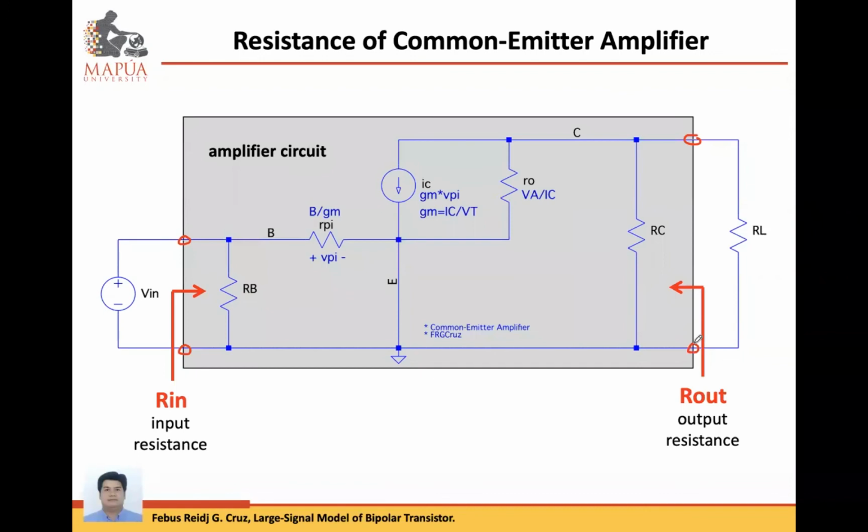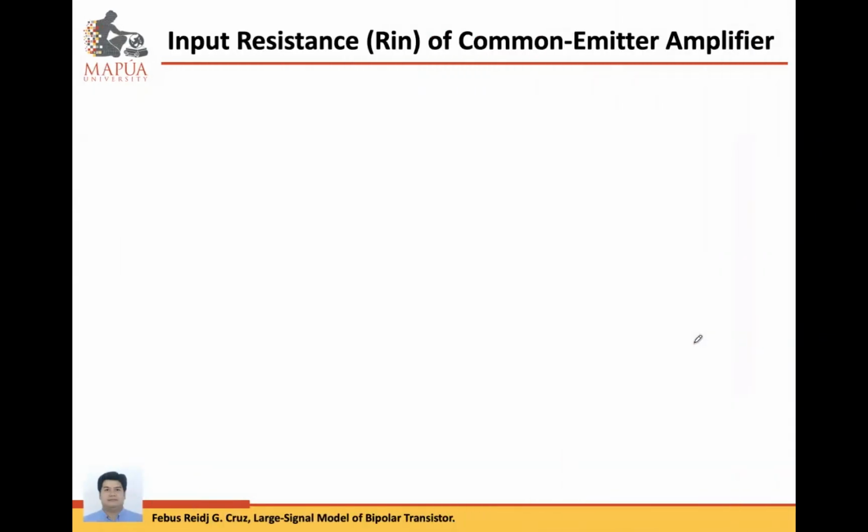Okay? So, ganyan yan. But, when you do the measurements, ito yung reminder. For the input resistance, so this is the amplifier circuit. If we want to determine the input resistance, we are going to remove the AC input voltage and apply a known voltage source Vx.